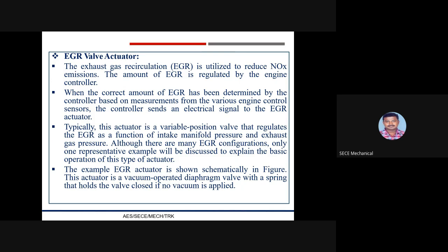So the exhaust gas recirculation system is controlled by the exhaust gas recirculation control solenoid. When the exhaust gas recirculation control solenoid is activated, a passage is opened up that allows exhaust gases into the intake manifold. So the exhaust gas recirculation solenoid is controlled by the engine computer, that is an electronic control unit or module. Okay, and it will activate at very specific times in order to achieve the best performance, efficiency, and emissions from the engine.